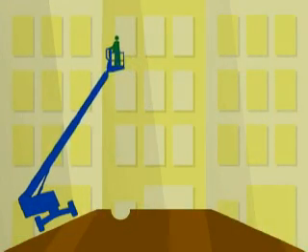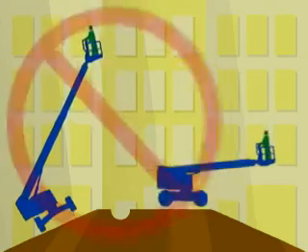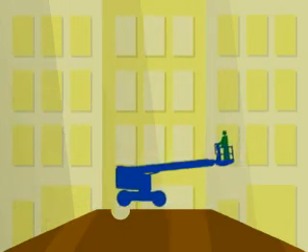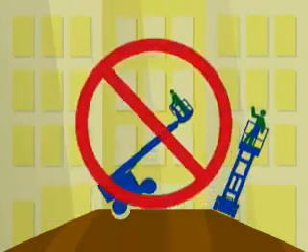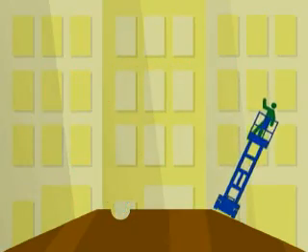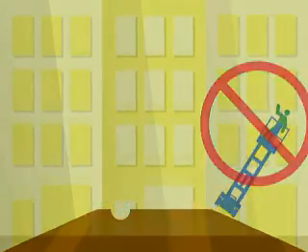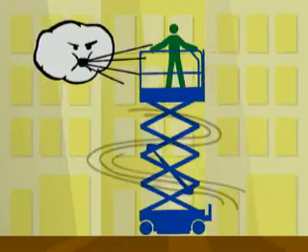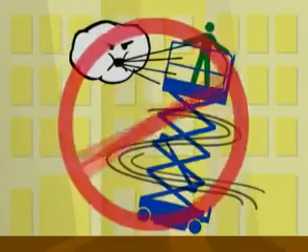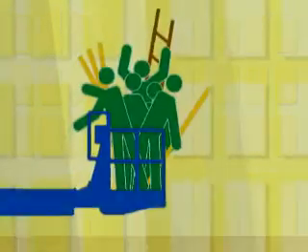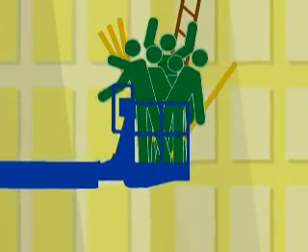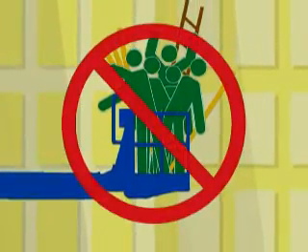Trying to operate equipment on unlevel or unstable ground conditions. Bad weather or windy conditions. Unsafe numbers of people or too much weight on the platform.